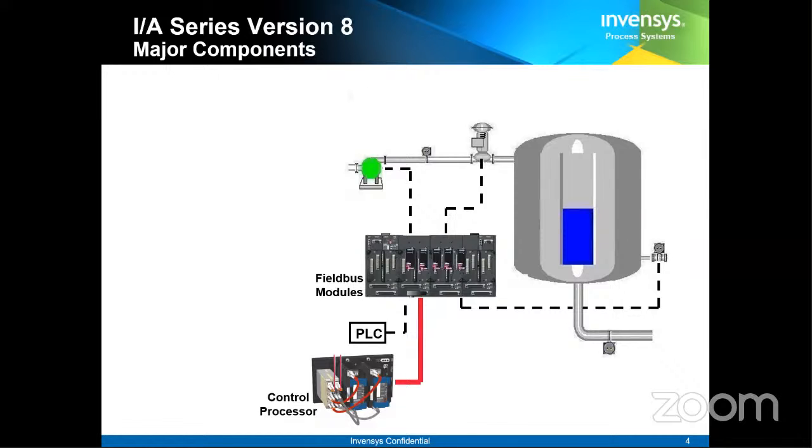For example, in this tank, I want to maintain the level at 75, but with a lot of effort, I am able to maintain the level at 79 or 78. So there is an error of 3%. That is called the error. Nobody likes error, so our intention here is to reduce the error as much as possible, right?